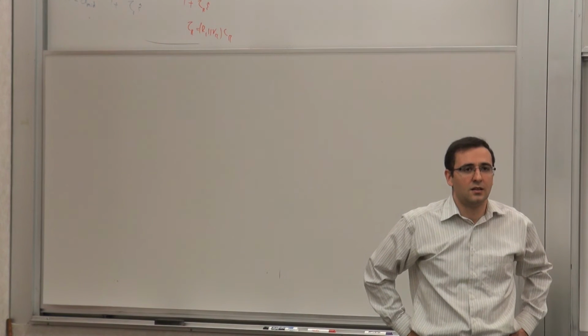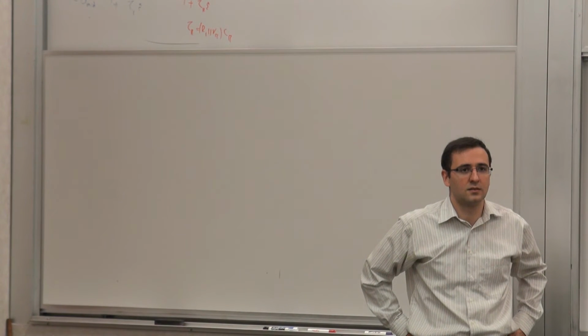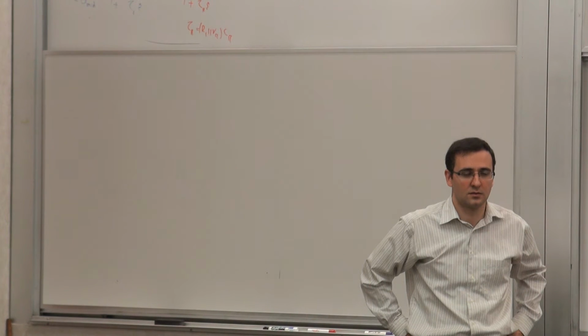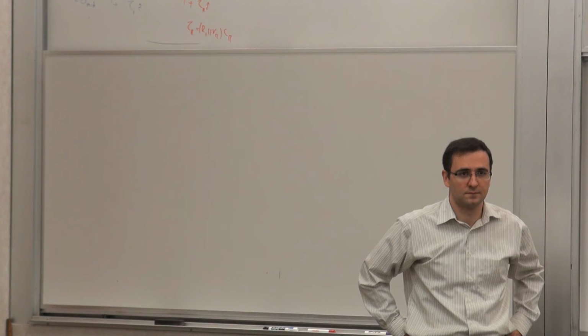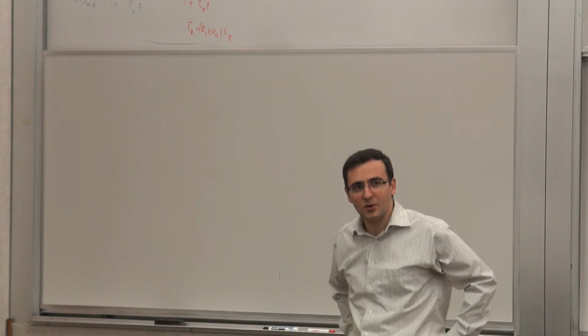You are calculating two transfer functions which approximately show the frequency behavior of that circuit, right? Right. For two different regions. But when you multiply these two transfer functions, the final transfer function, which is the product of these two, is the exact transfer function of the circuit, or is it an approximation? Not exact, no, it's an approximation.